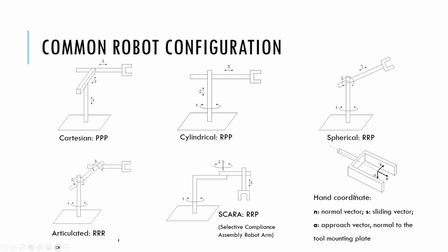I didn't talk about this here as well. Might as well bring this up here. All robots have some kind of end effector. I call it a gripper or whatever the tool is, and it also has an orientation. So it's a tool frame and a base frame. This N is normal, this A stands for approach, and then this would be 90 degrees from there.